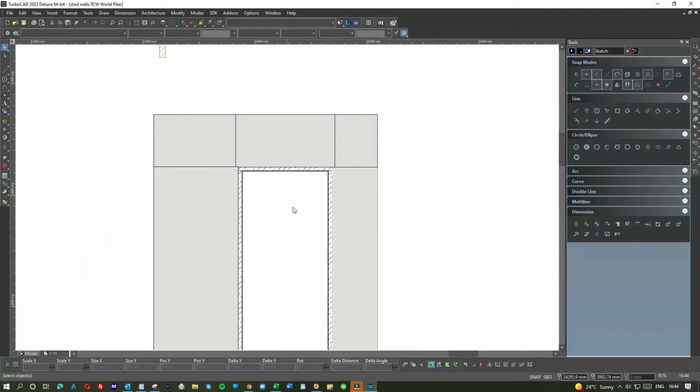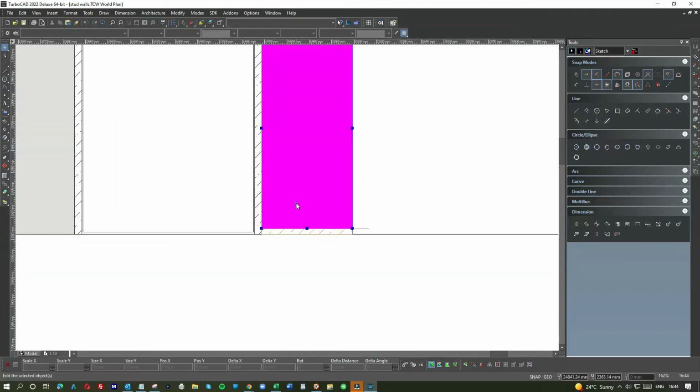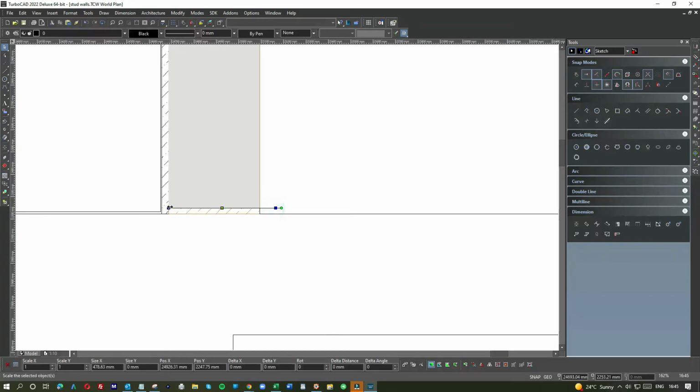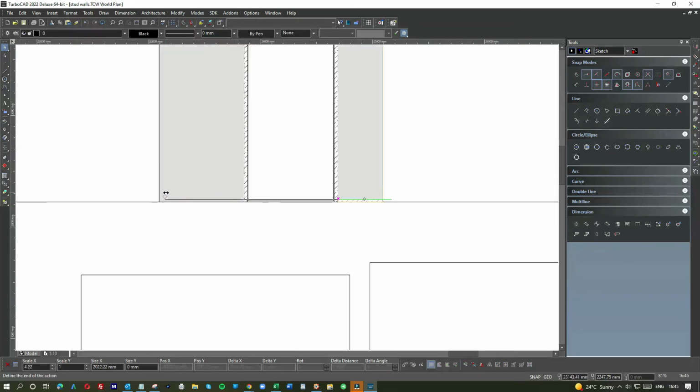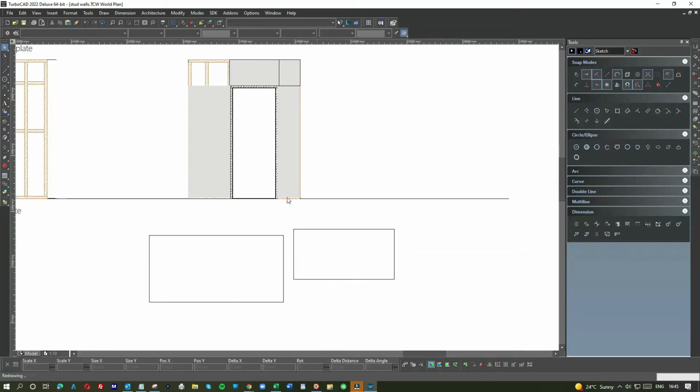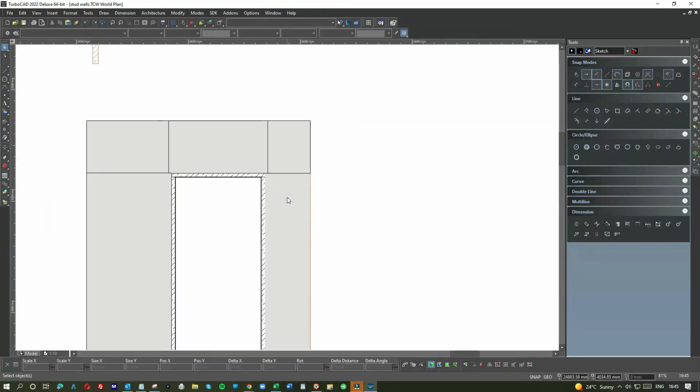So now we've built a wall. Oops, let me just, I've gone too far down, remember? I wouldn't normally do it down to the floor. So what I would do there now is keep the plasterboard just a touch off the floor. That's more about insulation rather than design. But if you're building and you're advising the builders, then advise them 12 mil up or 25 mil, half the sole plate, and that's a really good way of doing it.